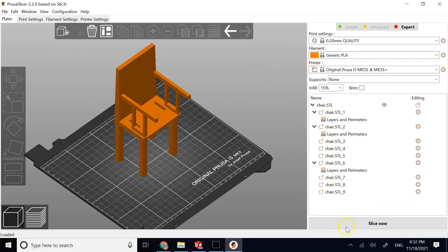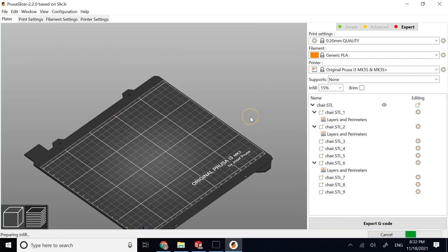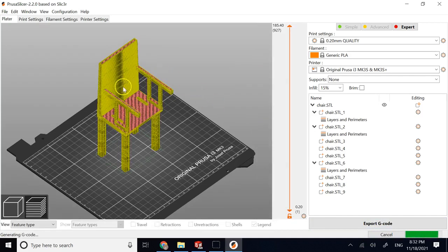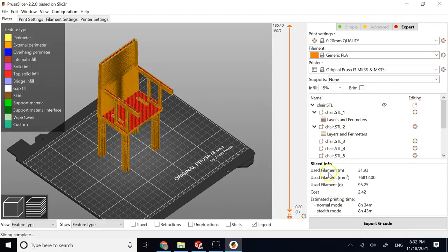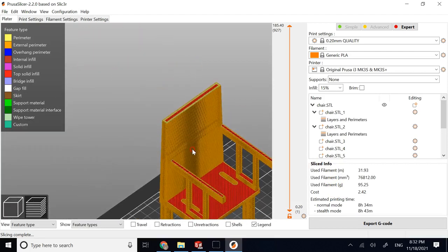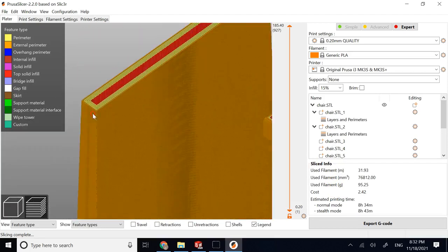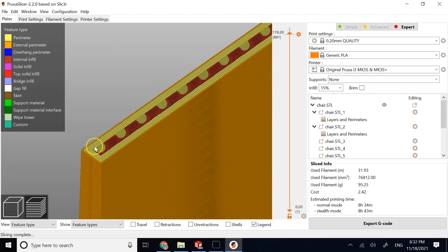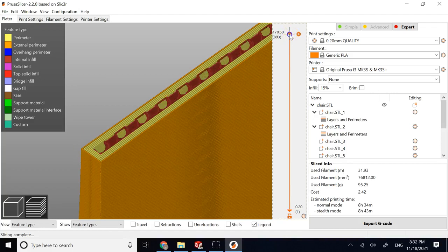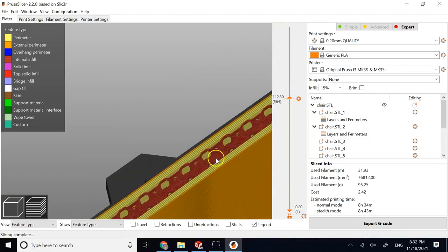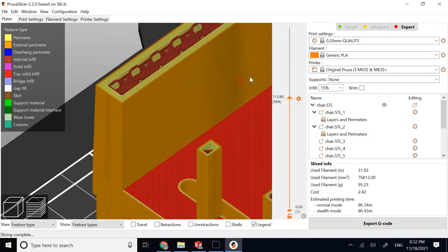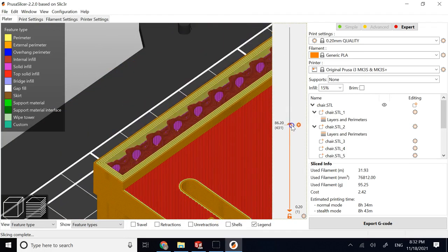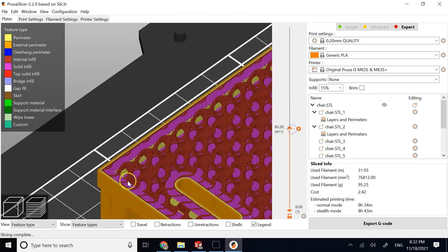So look, if I go ahead and slice it right now, then the number of layers for the back part and for the sitting area should be different than the rest, because I have 9 separate parts and I could customize each one. And now you can easily see, if I go to my sitting area, the back area, you clearly see there are 4 shells, right? Then if I go further down and I get to the cushion, you clearly see in the cushion I have what?